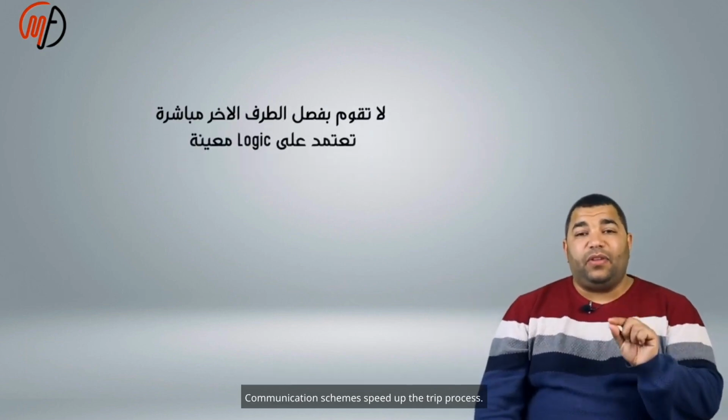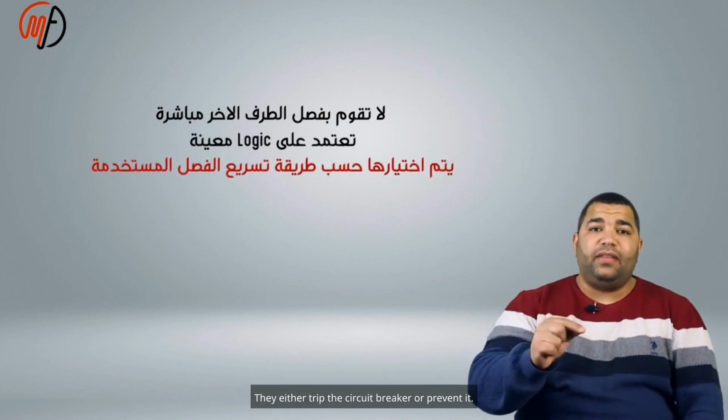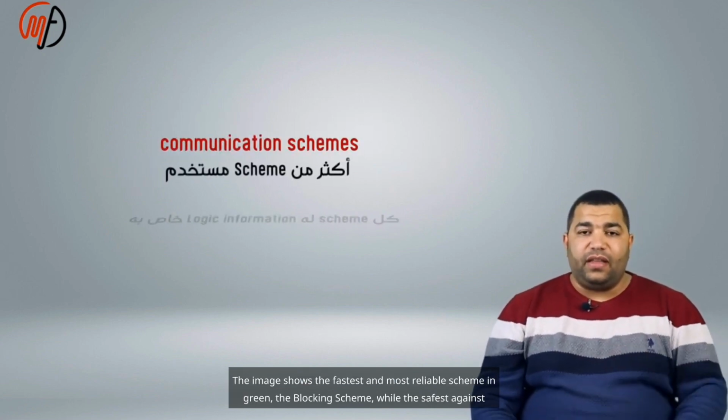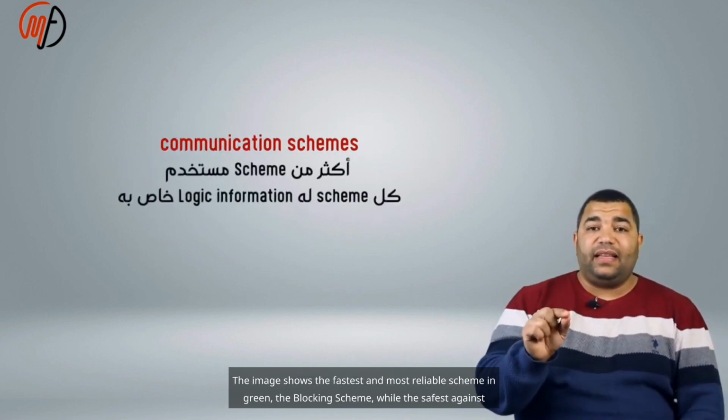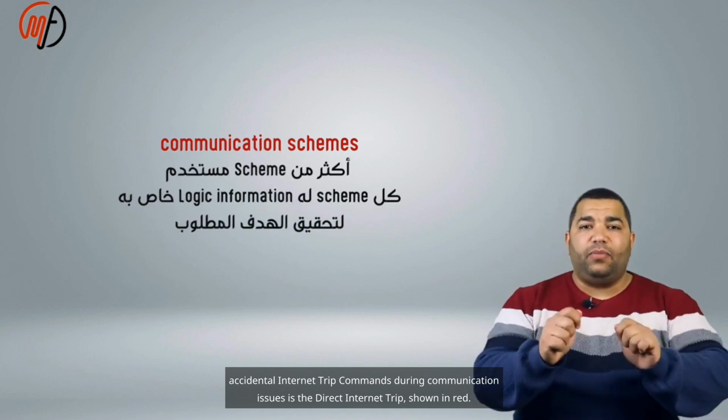Communication schemes speed up the trip process. Direct tripping, permissive tripping, and blocking are common. They either trip the circuit breaker or prevent it. Each has pros and cons in speed and reliability. The image shows the fastest and most reliable scheme in green, the blocking scheme, while the safest against accidental trip commands during communication issues is the direct intertrip, shown in red.